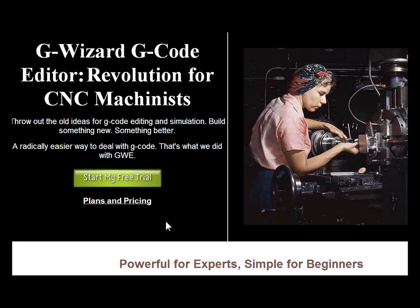I knew a guy one time, for example, that was running one of the major CAM packages, and he loved it. He had no problem with it whatsoever, but he was so happy to be able to run a quick simulation because every so often this particular program, when he used work offsets and multiple parts in the same program, when he went to the second work offset, the first part always worked just fine. The second part, every now and again, maybe 1 in 6 or 8 G-code programs, would just fire off a random rapid move back to someplace where the first work offset was.